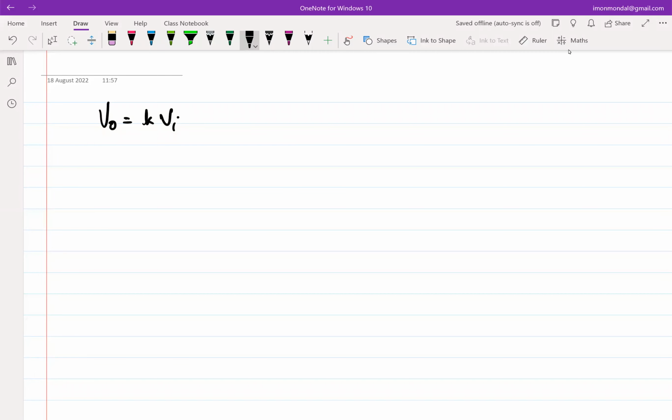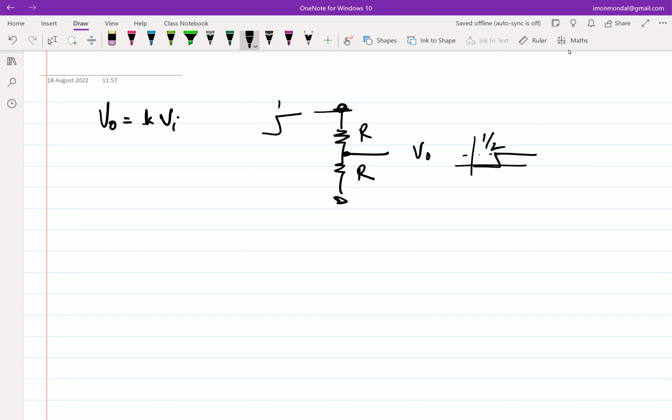Now, very briefly, you can imagine that if you put a capacitance in, let's say you have an R by R network, like a voltage divider. Let's say you have a voltage divider and you put a step at this node, and you're observing this intermediate node. If both are R, what do you expect this intermediate node to be? It should be a step again, but half of whatever it was initially.